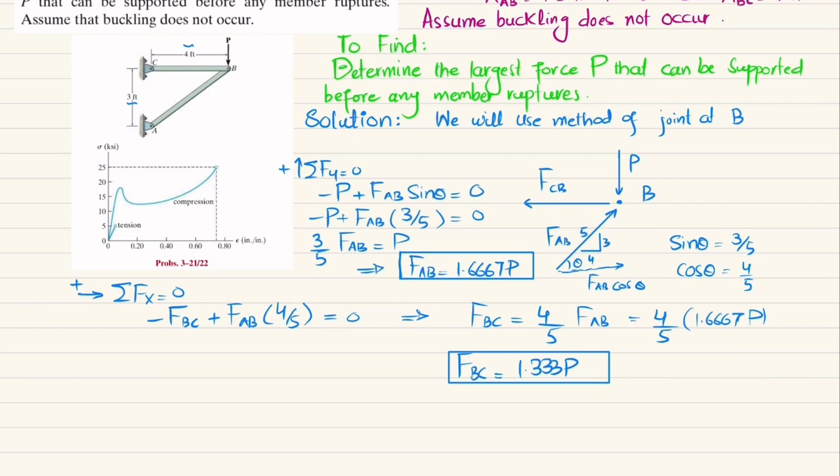So what we will do is that we will first assume failure of bar BC. From this figure, you can see that due to this load, the bar BC will be in tension. So you will use this stress strain diagram. From this stress strain diagram, the rupture stress due to tensile loads comes out to be 5. Clear? So we can write 5 KSI.